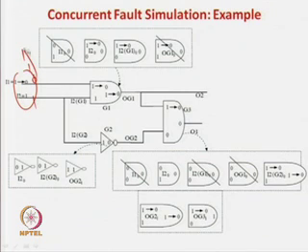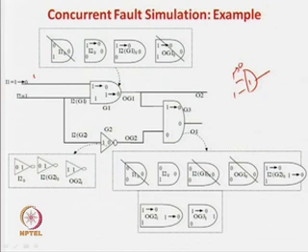As you have already seen in event-driven simulation, our computation will only be for those cases where there is a change. Let us see what happens. Initially it was 1 1 and the answer was a 1. Now there is a change in signal value, changing from 1 to 0. We will recompute only when things are changed, so the recomputation is 1 to 0. Here it is a constant, so the gate output is this one.